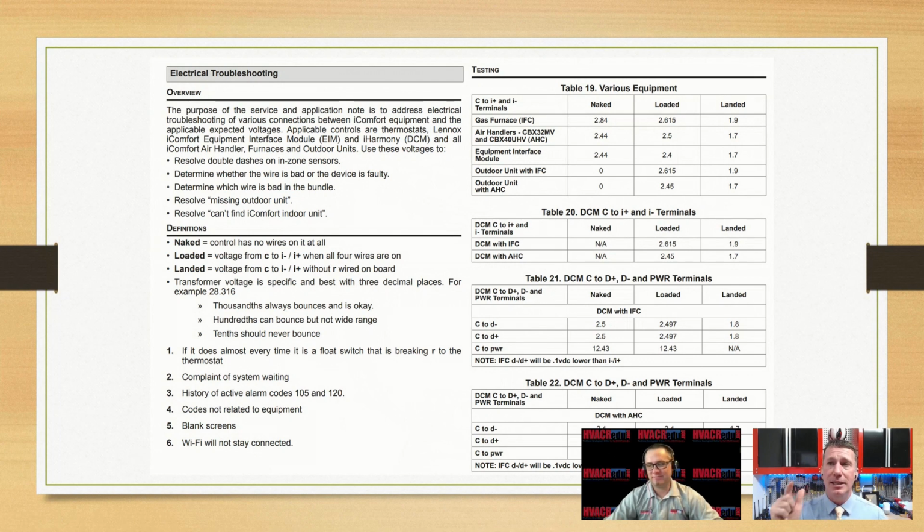If you're using anything other than solder, if you're using any type of solderless connector, make sure that you fill that with silicone or dielectric grease when you're done, so you don't get moisture or any oxidation down the road. I agree. Yes. All right. So another manufacturer debunked.